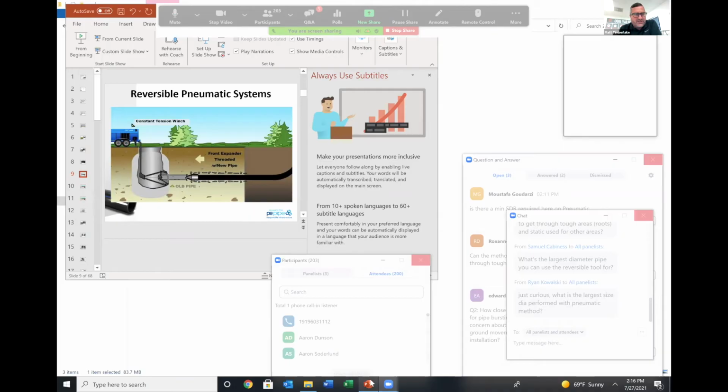And part of the reason is really because of that ability to use a small diameter reversible tool and to land in a manhole. Typical lengths can be laid out depending on soil conditions, ground conditions, lateral counts, things like that. But typically an installation is going to be laid out based on physically how large of a job site a crew can manage that day.